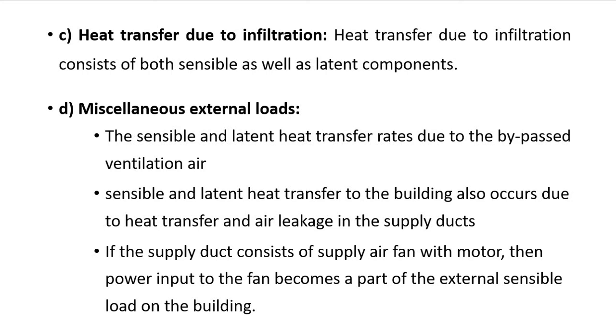In addition to that, the infiltration air also has some latent load. What is this latent load? The outside humidity level will be different. So when the infiltration air is entering into the room, it changes the humidity level in the room.